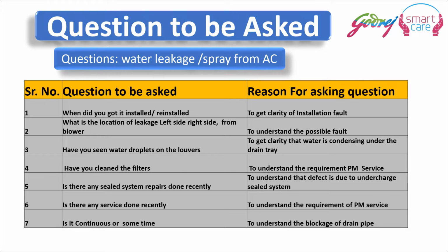Then we would ask the customer, have you cleaned the filters? That is, have you done regular preventive maintenance of this air conditioner, like cleaning of the filters or cleaning of the grills, etc. This is to understand the requirement of preventive maintenance service of the air conditioner, if it is not done. So we'll ask them, is there any sealed system repair done recently?